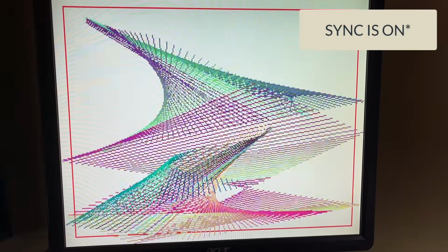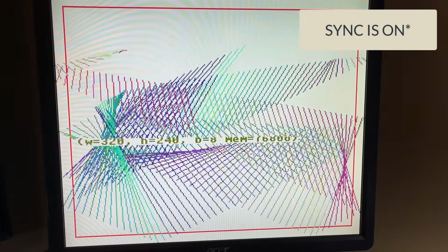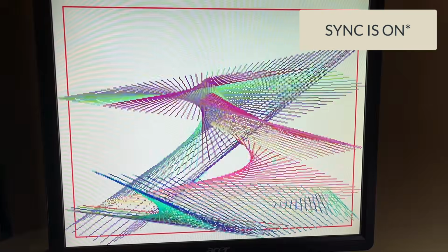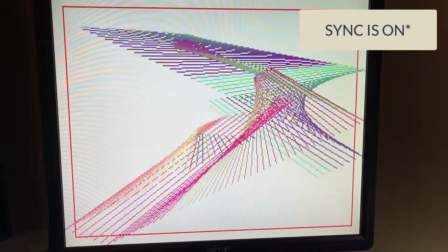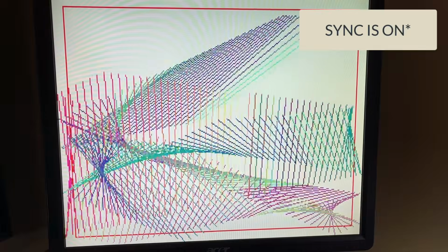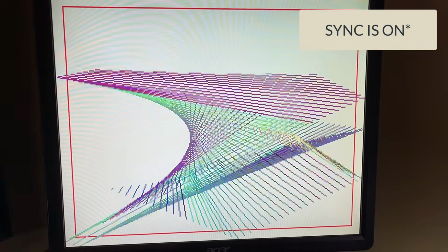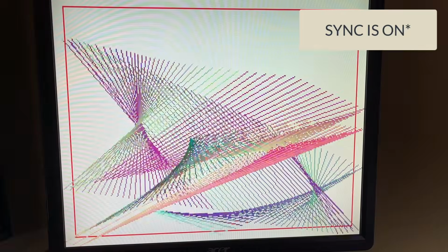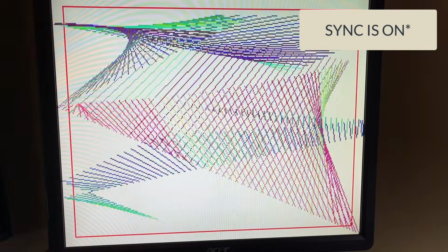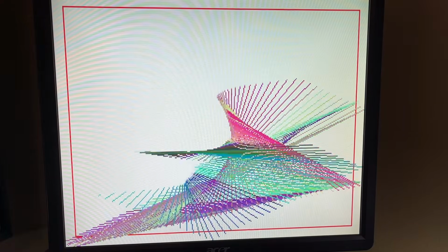What you may not notice here is that our nerd statistics are no longer showing in the middle of the screen. That's because it takes longer to draw this display than it does to display it. So there's not enough time for Core 0 to finish drawing all of the information before Core 1 takes over and draws the screen again. We can fix this by going into what's called double buffer mode. I'll talk about double buffering a little bit later. Now let's go to 640 by 480.